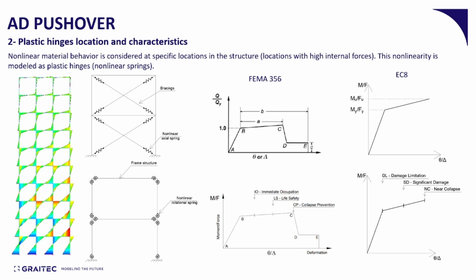So all those levels of deformation are combined with the different levels in terms of material nonlinearity back in the structural member diagrams, moment and rotation diagrams that we apply on the ends of the members.